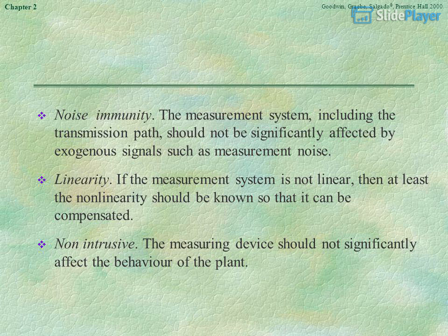Noise immunity. The measurement system, including the transmission path, should not be significantly affected by exogenous signals such as measurement noise. Linearity. If the measurement system is not linear, then at least the non-linearity should be known so that it can be compensated. Non-intrusive. The measuring device should not significantly affect the behavior of the plant.